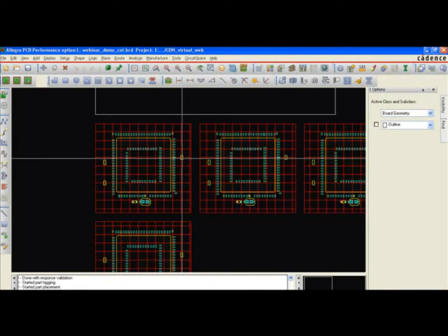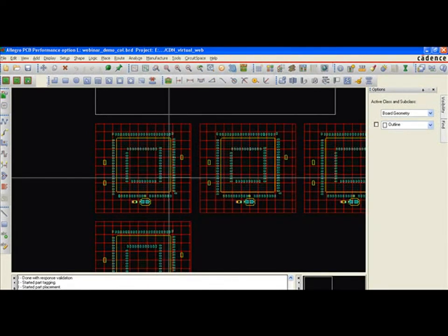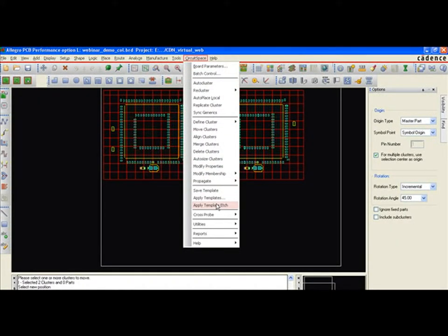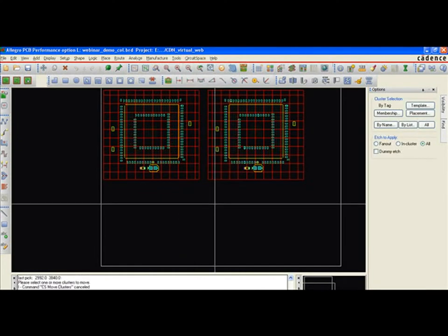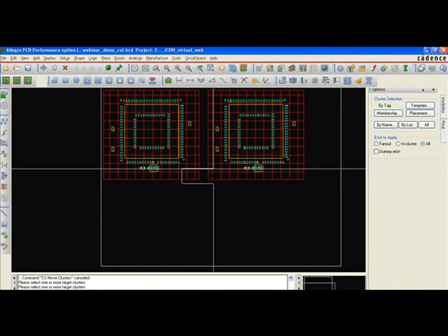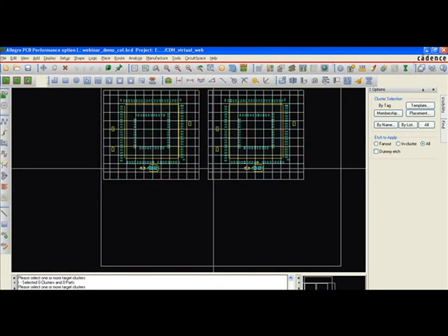You may remember that in the previous design, the etch was already complete for the circuit we used as a template. In this case, the layer stackup is different between the template design and the current one. Being a flexible reuse methodology, CircuitSpace allows you to map the old stackup to the new one, so you can maintain the etch from one design to the next.